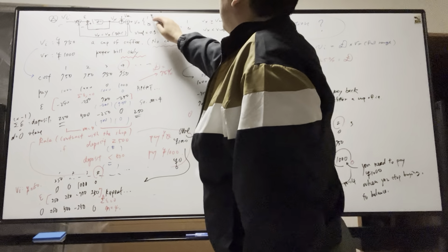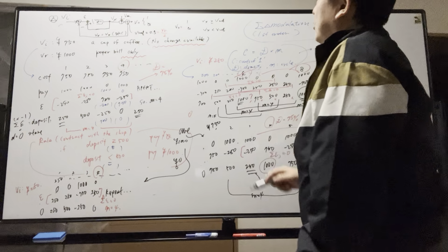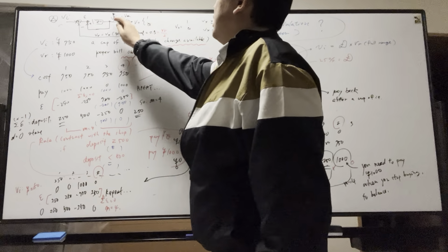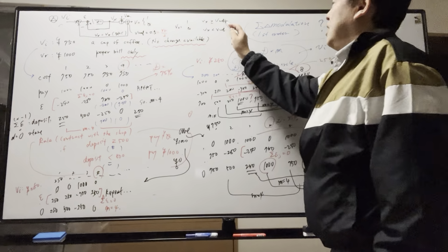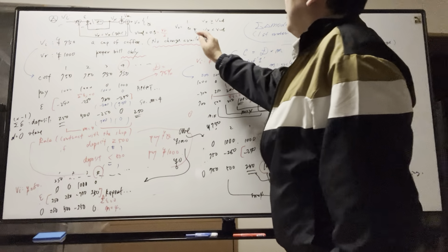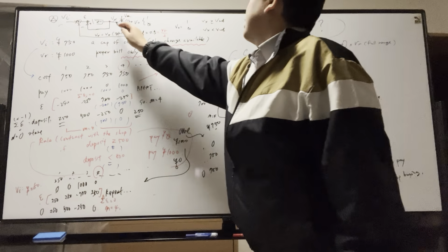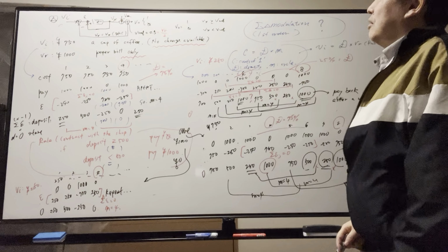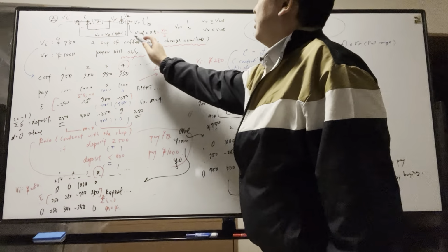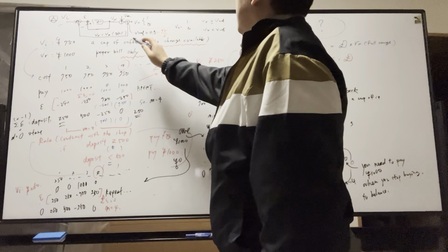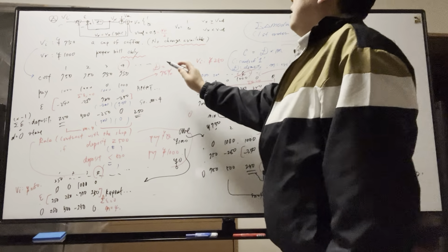Vout equals 1 when this accumulated value Vx is larger than or equal to Vref, or 0 when Vx is less than Vref. This time Vref equals 0.5, which is VR divided by 2.